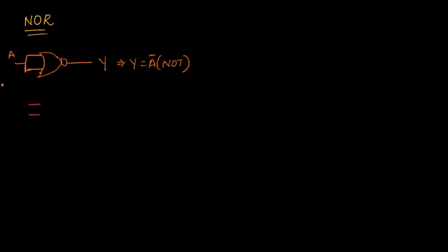Okay. Now let us see the other one. Using a NOR gate, how can we realize OR? So we can do this, and we are using two NOR gates here. Okay, this is A and this is B. By NOR you will be getting A plus B whole bar. To invert it, you need only A plus B. You don't need A plus B whole bar. So you are getting Y equal to A plus B in this scenario.